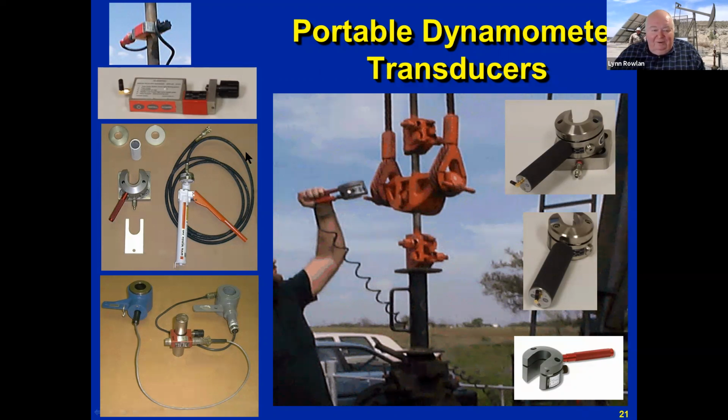So the advantage of the load cells is they're very accurate and they actually weigh the rod string. The advantage of these devices are they're quick and easy, and people tend to like to use these a lot because they're so fast. The other option you have is you have a pump off control system, or you have permanently installed what we call donut load cells, or pump off controller load cells already installed in your well. Then you can send us a cable and we'll fix your cable to hook into an accelerometer or the wired polished rod transducer. And you can use your load cell for load and our accelerometer from the polished rod transducer or the special accelerometer here to get the position of the polished rod.